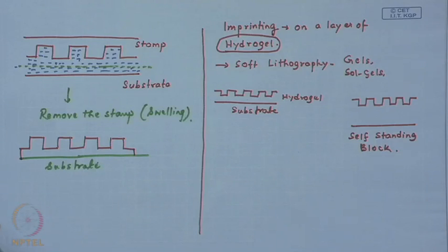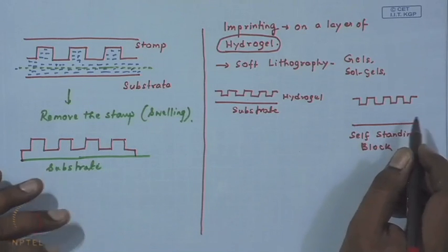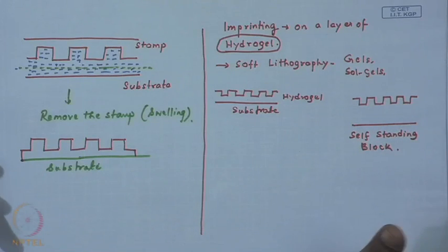Hydrogel is liquid like at room temperature, you sort of place the stamp and you get a negative replica. And then what was done, so after this layer was patterned, it was now allowed to shrink with evaporation of water. Now, the moment water starts shrinking, there is significant volume reduction, which can be of the order of 60, 70 or even 90% depending on the initial water content.